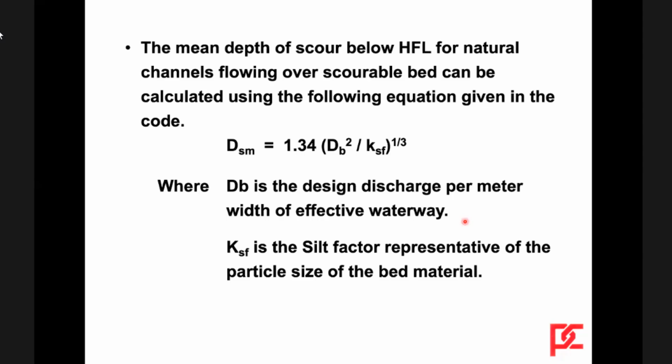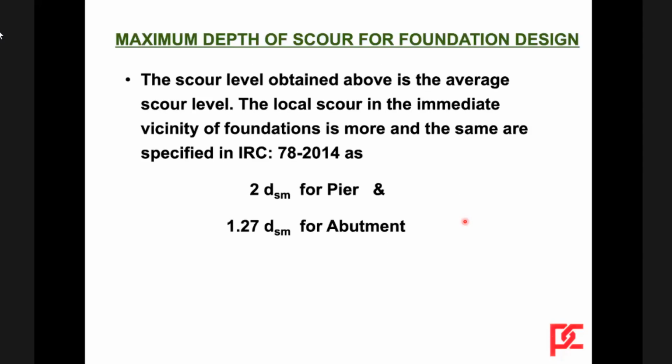And after this, once we get the scour level, for the maximum depth of scour for foundation design, because of the local scour effects and all these things, IRC 78 gives you an increase in the scour as twice dsm for pier design and 1.27 dsm for abutment design.